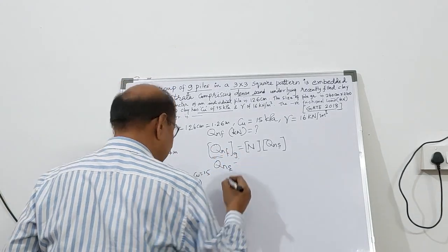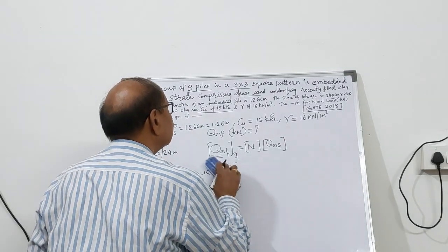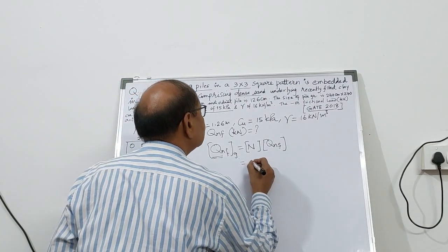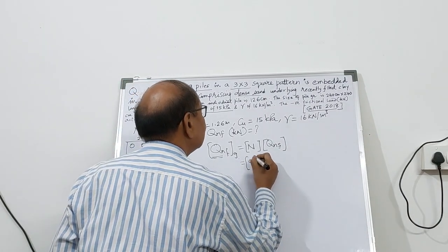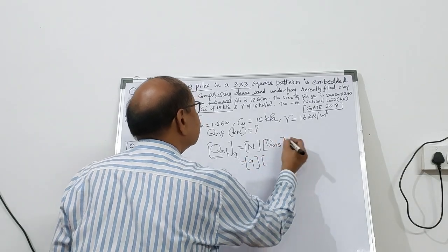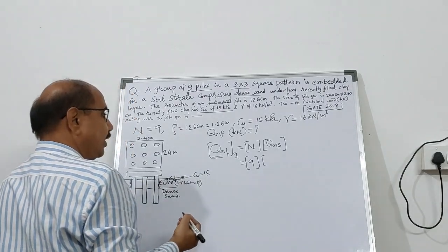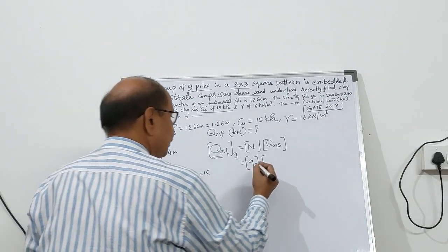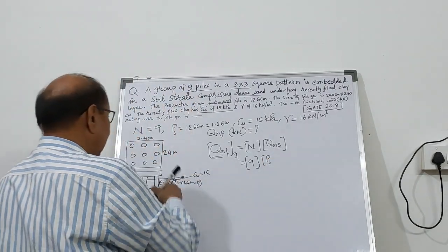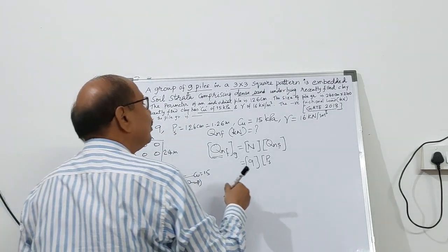The number of piles is known to you here, so based on individual shear it is 9. For the single pile, it will be the perimeter of the pile, and the friction is going to develop over the perimeter.